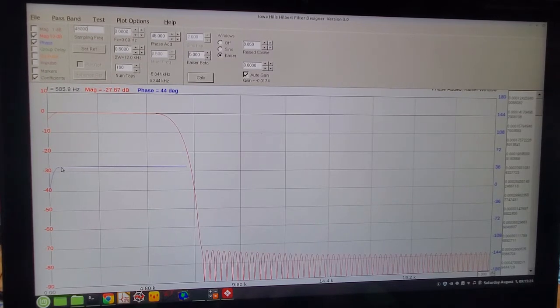But you can see that as you go down in frequencies, you start to get this sort of roll off here, and the phase deviates from that 45 degrees. So it's kind of not good below about, let's say, 375 hertz in this case. So you kind of have to do something about that, either filter it out or what have you.